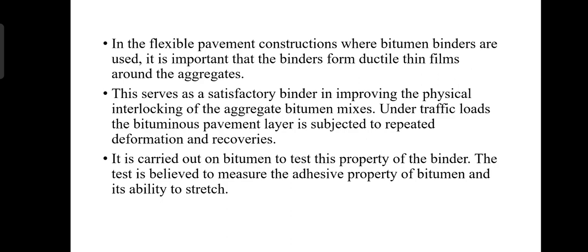Under the traffic loads, the bitumen pavement layer is subjected to repeated deformation and recoveries. The ductility test is carried out on bitumen to test this property of the binder. The test is believed to measure the adhesive property of a bitumen and its ability to stretch.